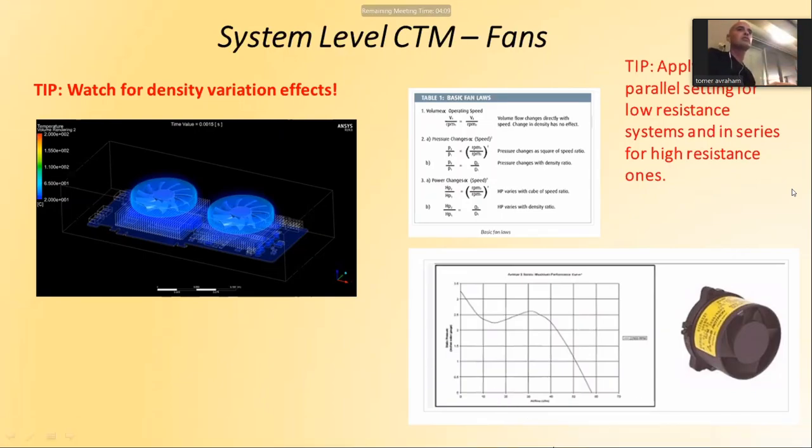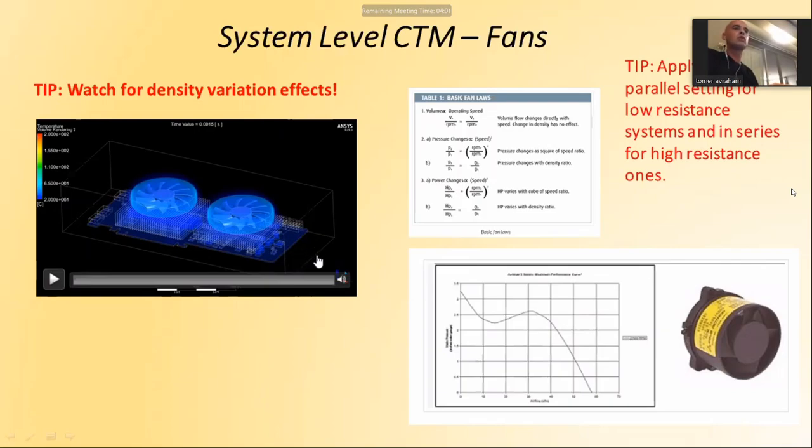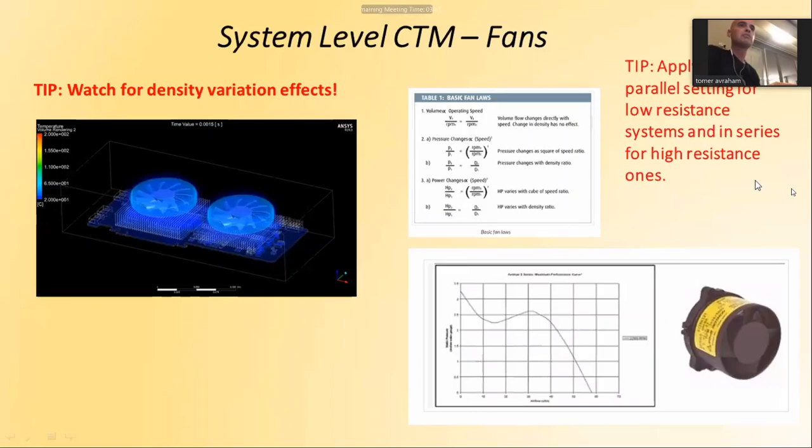So if you don't know which fan to use, if you don't have enough experience, always consult someone. There's also the issue of noise. This fan is noisy as hell. I mean, it actually screams when it works. And it could be a real problem. It could even be a restriction.